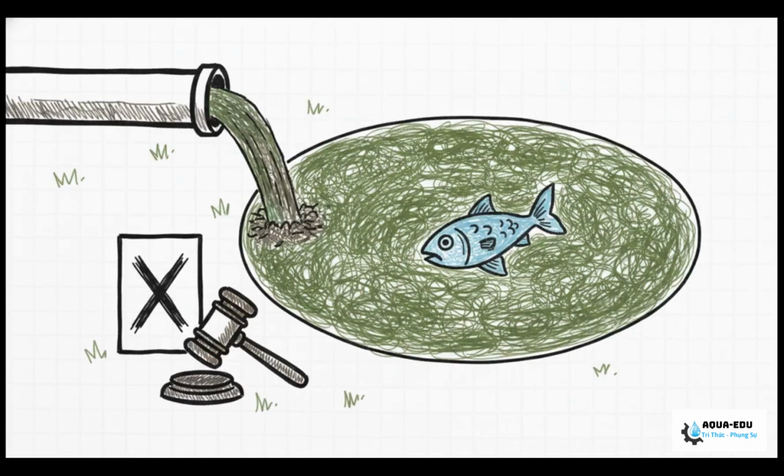And that, unfortunately, brings us to Incident 17. This happens when your effluent total phosphorus, or TP, blows past permitted limits. Typically, we're talking anything over 0.5 to 1.0 milligrams per liter. When you hit those numbers, you're not just risking immediate massive fines for the plant. You're risking severe ecological damage to the receiving waters. Think toxic algal blooms and total oxygen depletion. It is a nightmare scenario.